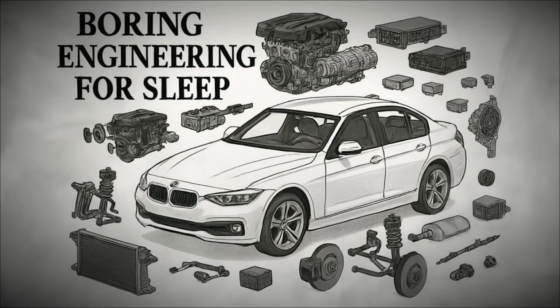Heat management is an ongoing challenge in brake design, since converting the energy of a fast-moving car into heat generates extreme temperatures. Ventilated discs, drilled rotors, and performance pads are used in some vehicles to handle these conditions. Brake systems must also be inspected regularly, as pads and shoes wear down with use, rotors can warp, and hydraulic components can leak. The purpose of the brake system is ultimately to give the driver confidence and control, ensuring that the car can always be stopped safely.